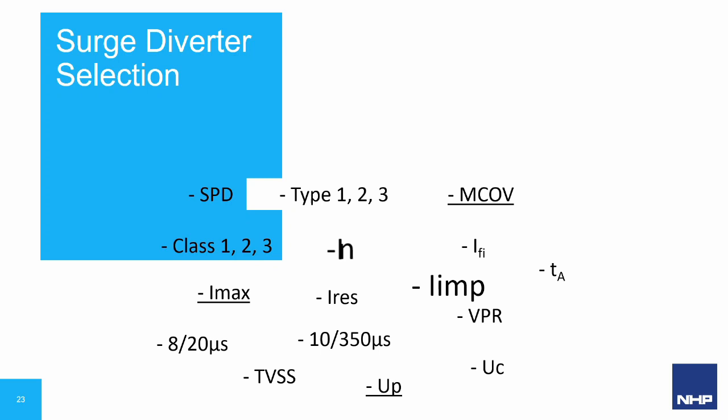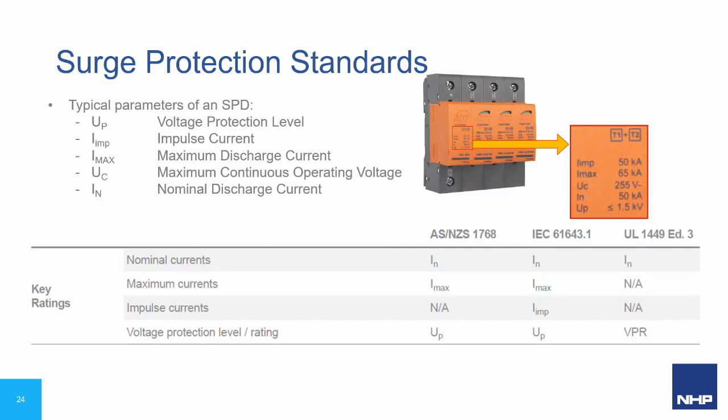But having three standards puts us in a unique situation, as most countries are aligned to either UL 1449 or IEC 61643, but not both. This allows us to use product design for either the American or European markets. However, this causes issues. These standards sometimes have the same symbols, however, each standard has its own tests behind those symbols, which can vary between the standards. The next few slides will aim to explain what the symbols mean and how they differ between the standards.